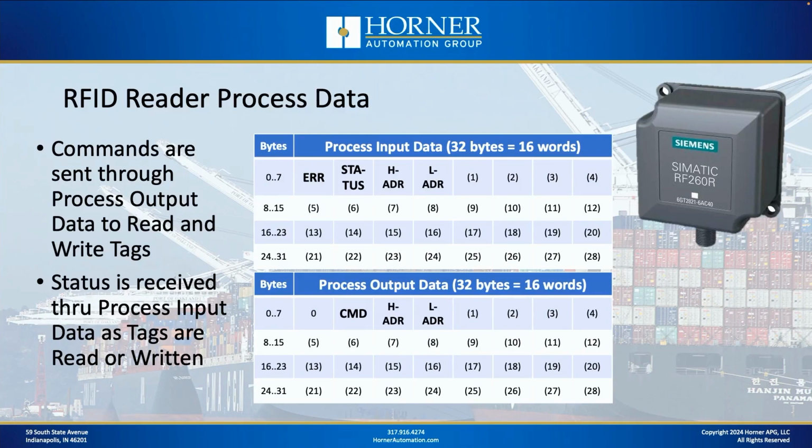So for the input side of things, we are monitoring status. We are monitoring or taking a look at data bytes. Those are the numbered bytes you see there on the screen. And that's where the read data will ultimately be located for us to copy into our program into other variables.